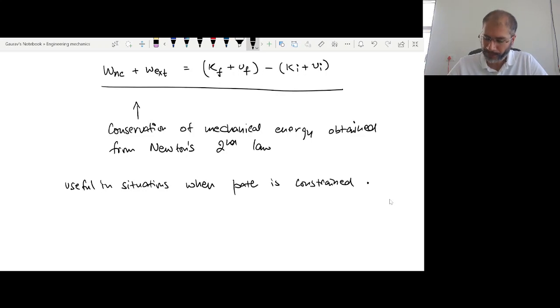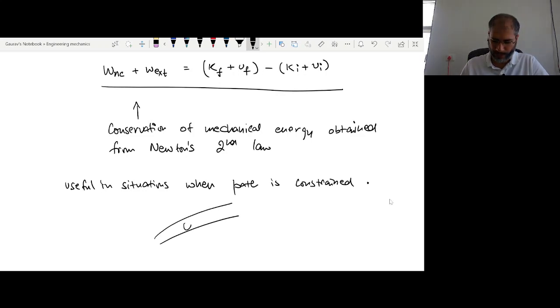but its velocity may not be known as a function of the position in the path. Okay, the other interesting thing is that whenever you want to constrain a particle, let's say in a given path, so the particle can only move in this path, then the path for some reason will apply a constraining force. Otherwise the particle will have a tendency to go anywhere. So if the particle tries to leave the path, the path applies a constraining force, and this we call Fc, the constraining force.